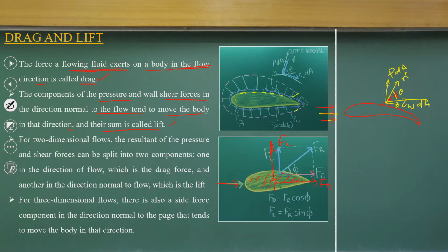We are not going into details, we are just looking at it, and this also has the pressures. If I have the pressure field, and I know the wall shear stress, then with a very simple force component resolution, just computing the component in this direction as well as the perpendicular to this: this direction is the drag force direction, and this is the lift force direction.